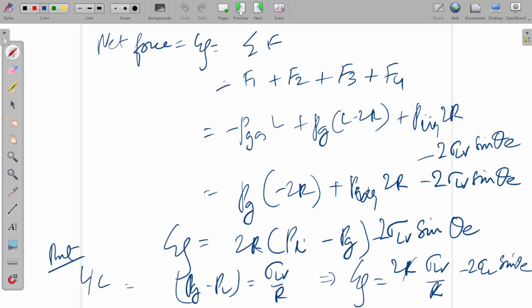So on Wednesday or Thursday, I'm going to talk about lubrication theory. Lubrication theory assumes that you have this precursor film. When you have a precursor film, you're not having a contact line. You're essentially sitting on the same fluid, so you don't have the issue of the energy going to infinity there. While having a precursor film is a mathematical device, as I'll employ, in experiments we actually do find that there is an adsorbed film. So precursor films are not a figment of mathematical imagination.